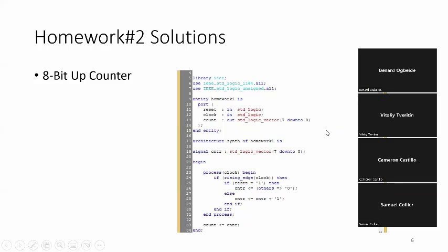Did you figure out how we can make it asynchronous? So, from what I understand, in your begin syntax and everything like that, you have the clock first, and that's what makes it synchronous. Everything depends on it. But to create an asynchronous counter here, you want it to be independent. So, would you create a clear that is prioritized first? How could I create it? You would have to create another input with a clear. Where should I put it? Well, first put it in your ports. Create a clear port. Okay, input. Okay, I'll put a clear port.